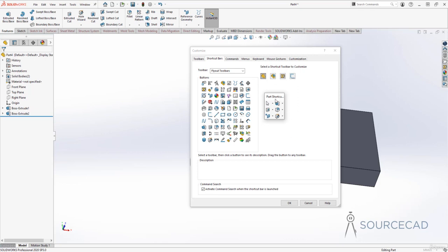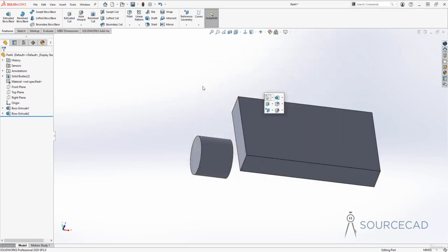So for that, you don't need to go to sketch environment. You just need to click on this sketch and this will show you the sketch shortcut panel. So from here, I'll just select the point tool, which we added in the example just a couple of minutes before. So I'll drag it and drop it out. So again, we are left with the default tools and I'll click OK. And that's the shortcut key. And this is how you can start making simple things in SOLIDWORKS.